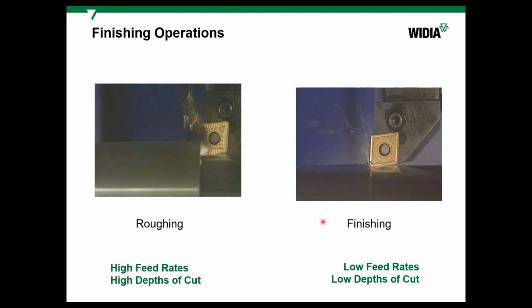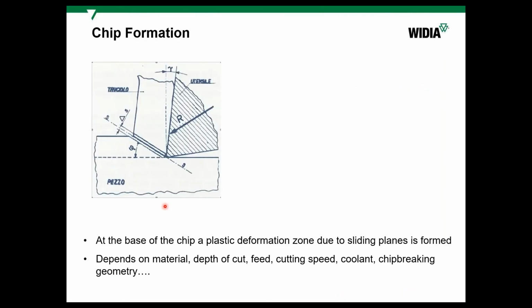Here in these videos, you can see how these operations differ, roughing operation and finishing, basically because of the depth of cut and the feed rate.